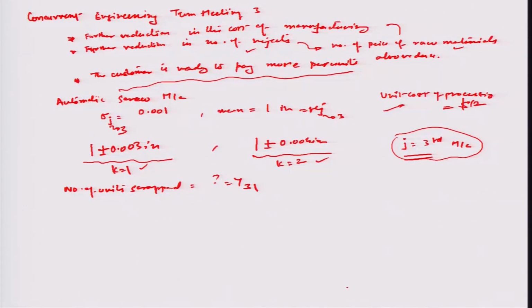using the third machine on the first specification, okay, YS 31, and as you know, this is equal to KS 31 times of the output unit Y 031, and we can find out the KS again by looking into just the scrap fraction. Okay. So, you know that KS 31 is also the total scrap coefficient 31 divided by 1 minus scrap coefficient 31. Okay. So, in this particular case, we need to determine what is the scrap coefficient, and scrap coefficient can be found out again from the upper and the lower tolerance limits.